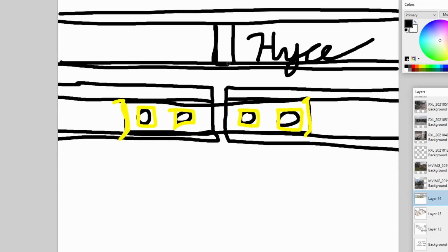But you'll see this extra brick where they'd actually had their welded joint. So the head of the rail is now seamless, so you don't get the bang, bang, bang, bang of the transition across. You have less maintenance, a smoother ride, and you're allowed to go faster because of that. This is a much stronger bond than this.